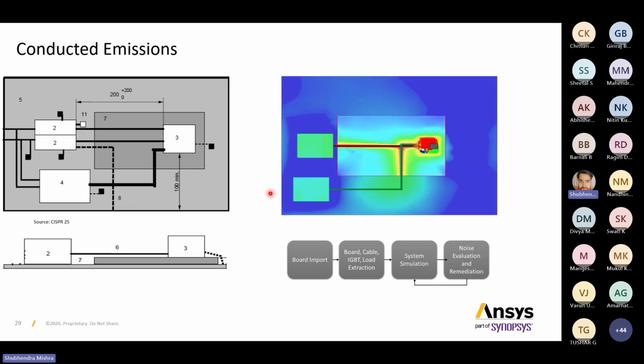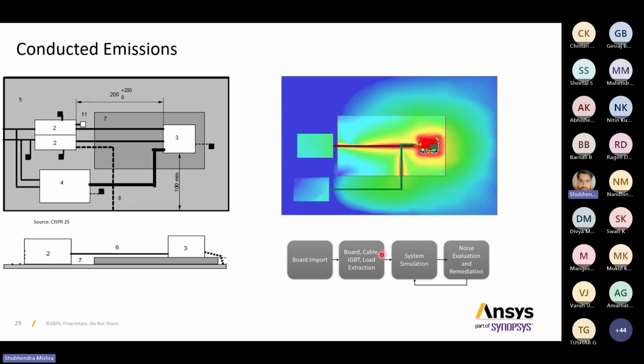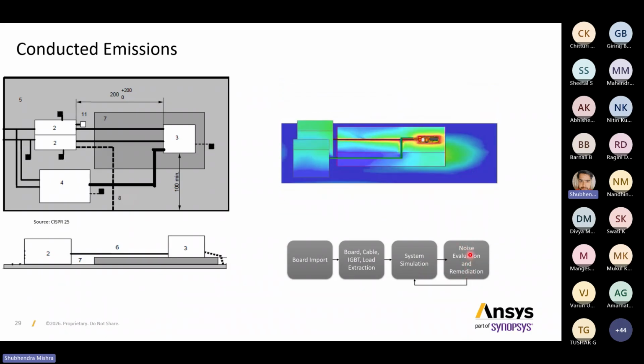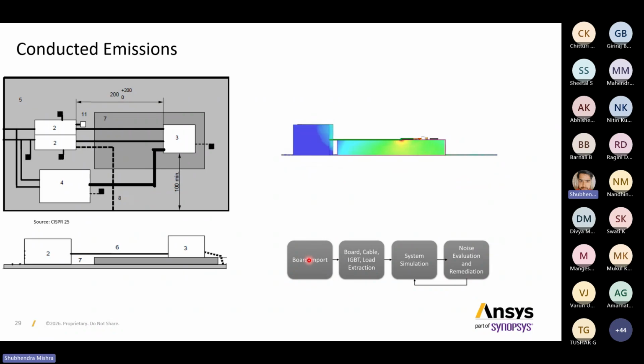The basic step is importing the board file, then going with the extraction part, doing the system simulations, and evaluating the noise. If you're facing some problems, you don't need to import the board file again. You can directly go to the system simulation, make some changes, and evaluate again.